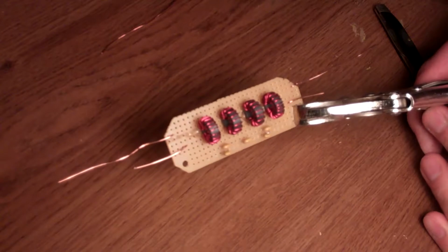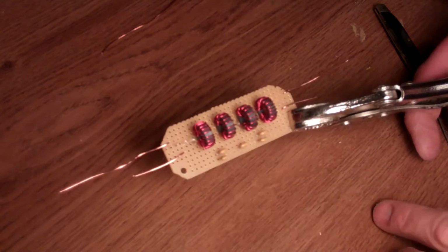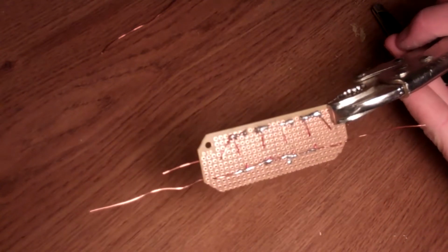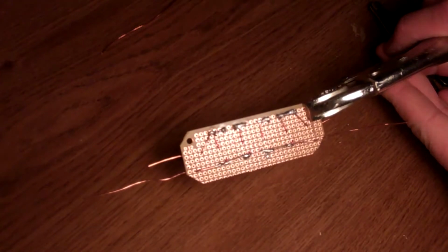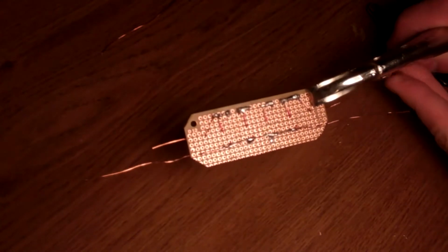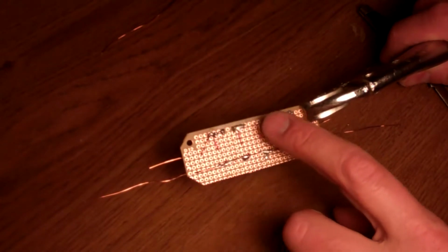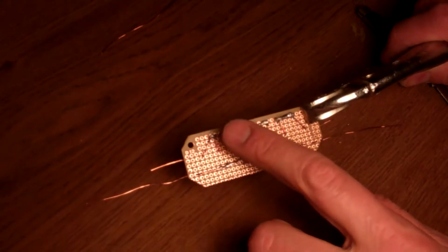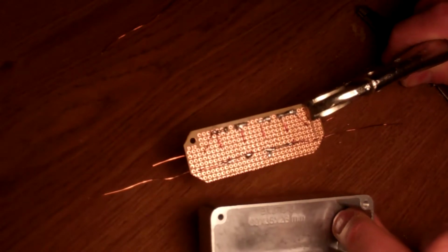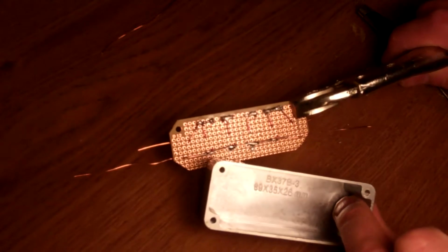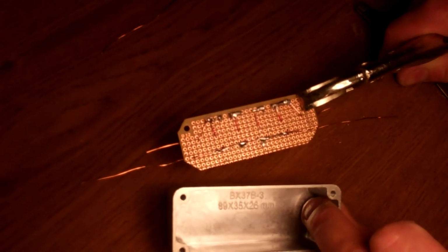So here's the completed filter board. You can see the seven different poles. Soldering job's all done. It's ready to fit and put inside the box. I'll put a little tape over the areas that are not part of the grounding bus, just to make sure that they don't come in contact with the aluminum box. So that'll kind of clean it up a little bit and make sure that contact doesn't happen in the wrong spots.